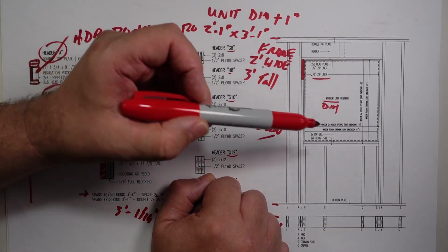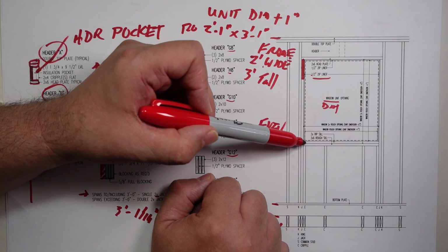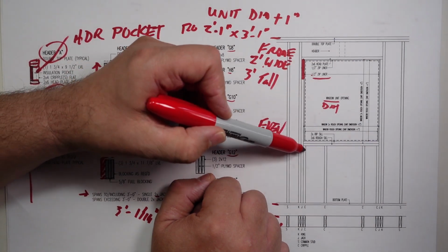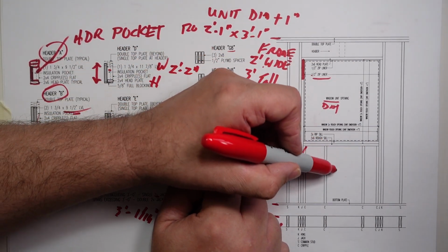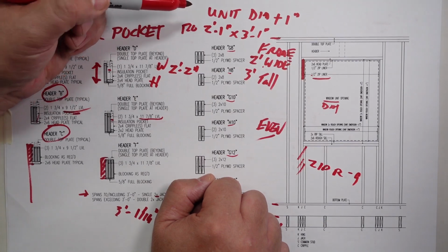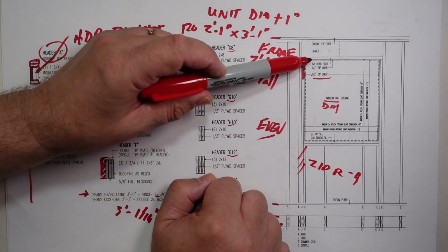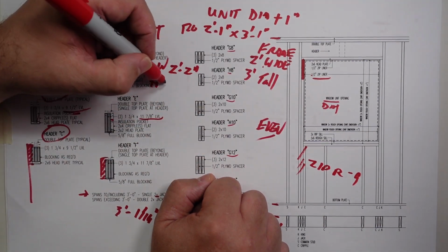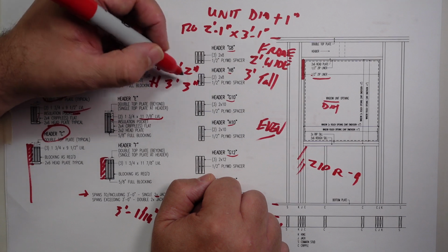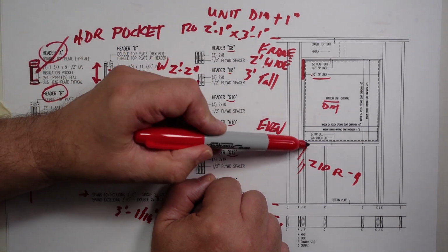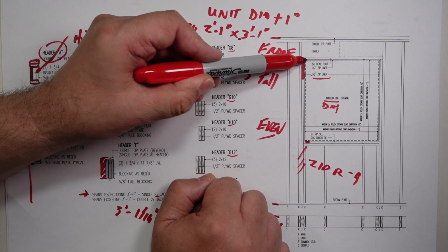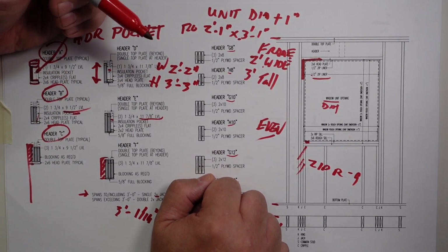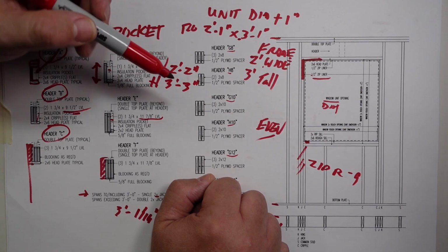Now the height is a little different because I add what I call the rip sill, and that's basically a sill that goes all the way back over the R9. This is assuming that we have zip R9 out here for this project. So that 1.5 inches plus the 1/2 inch there is 2 inches plus the 1 inch. So that is 3 foot 3 inches, right? It's the 3 foot 1 plus the 1.5 inches of the rip sill plus the 1/2 inch zip liner that goes there to maintain our weather resistive barrier continuity.